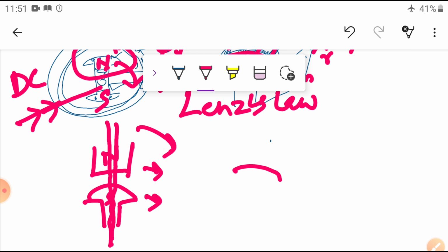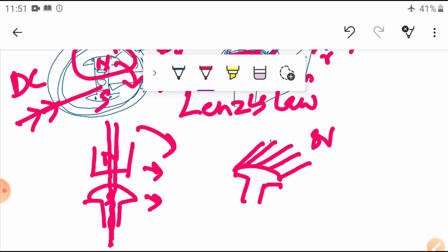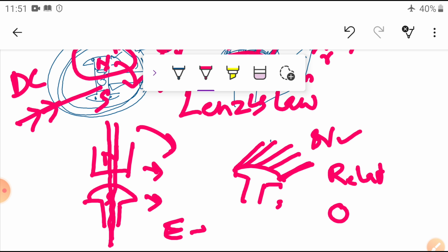What is the position of the copper bars, that is, the damper bars? In this case, what will happen? The stator magnetic field and rotor are both running, so the relative motion between the rotating magnetic field and the copper bars is zero. As per Faraday's law of electromagnetic induction, to induce an EMF, a conductor is required, a magnetic field is required, and relative motion is required.